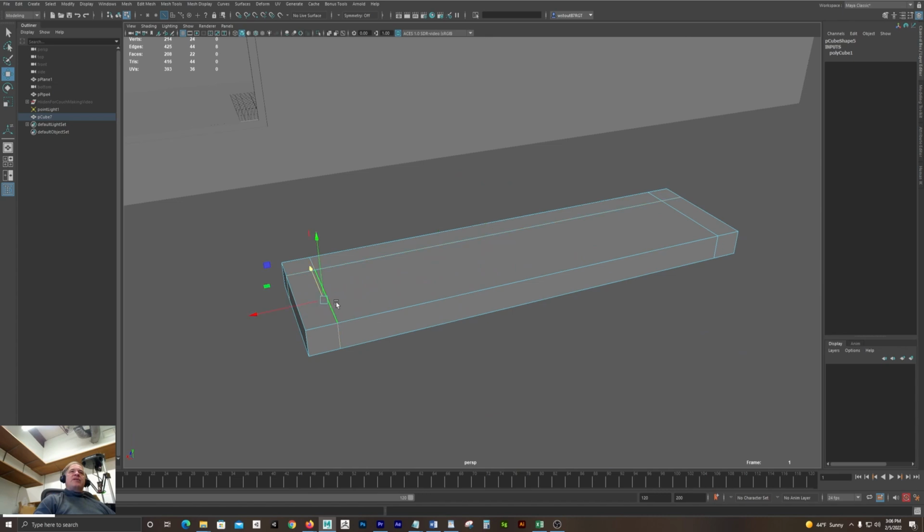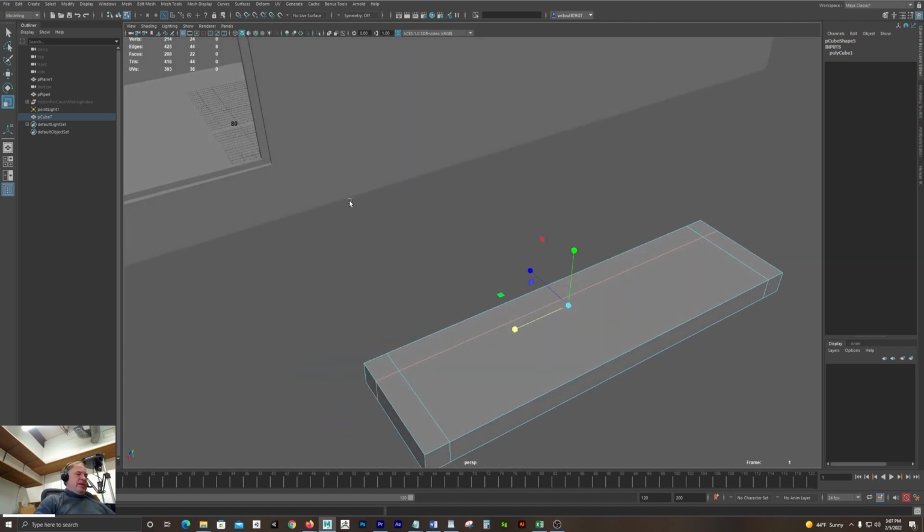And notice when I had 2 edge loops selected, I can use the scale tool to move them equally, so they'll be symmetrical. I don't have to turn on symmetry or anything like that. I can just use that scaling tool to move 2 objects through space. For one, I had to switch to the move tool to move it because I'm not scaling it against anything.